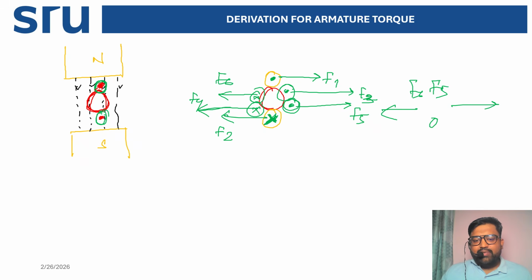That's why there may be a condition that at some time it can stop if there is only one conductor. But we know that the armature contains many conductors, and that's why we denote the conductors as Z. Z equals the number of conductors. When one conductor is in this situation, the other conductors will take care, and by which you see it will get a rotational force.